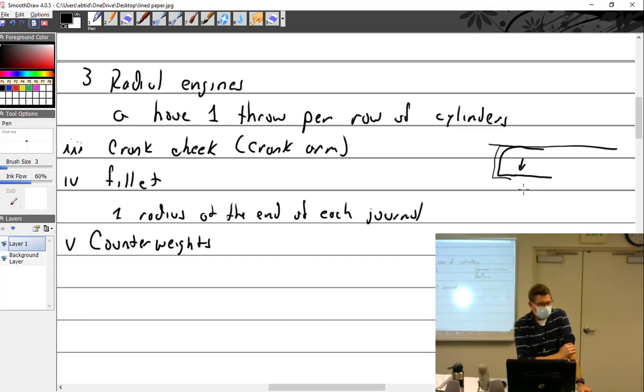So I would just tell you that you have to be extremely careful when you're putting counterweights together. Because there are just so many inspections on those counterweights. There's an area called the bump stop area, and you can see that it actually slaps up against the crankshaft. So it's hitting right here.